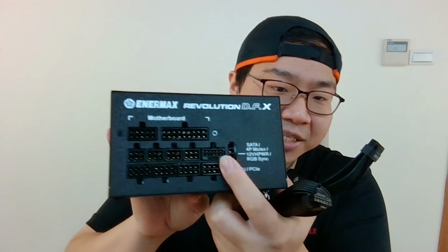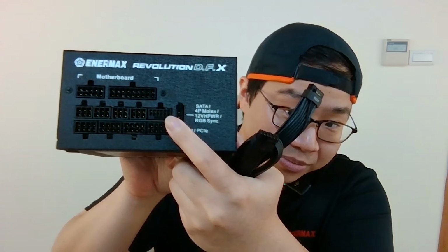They're the same thing. The difference is, for some power supplies like our DFX, we have a native outlet for the 16-pin cable. But some other power supplies, like our DF2 or Corsair's, I think it's RNE series, they don't have a native outlet for this. So they need to use an adapter. The adapter usually has one side that is an 8-pin, the other side that is 16-pin. But it basically does the same thing.